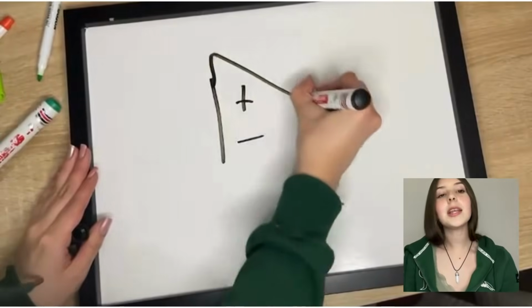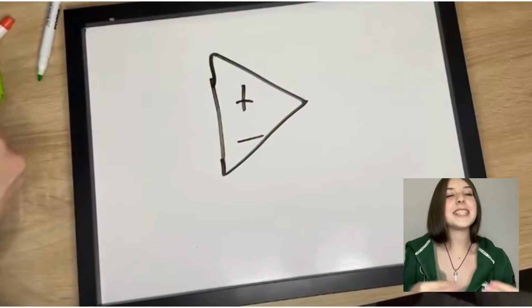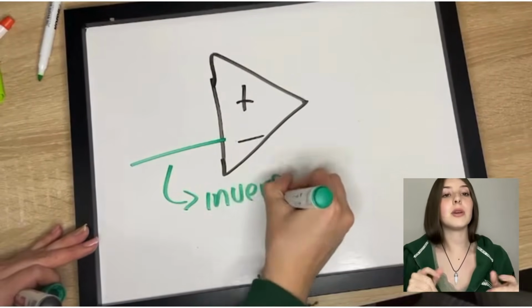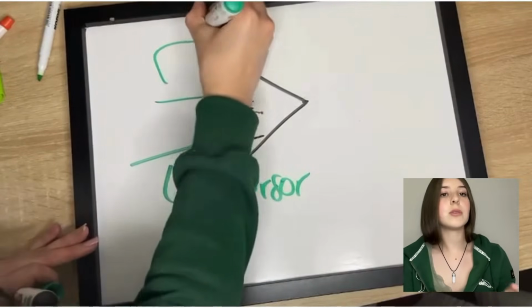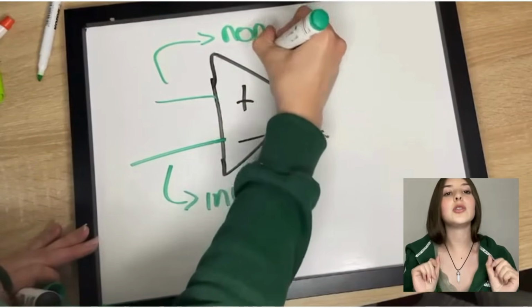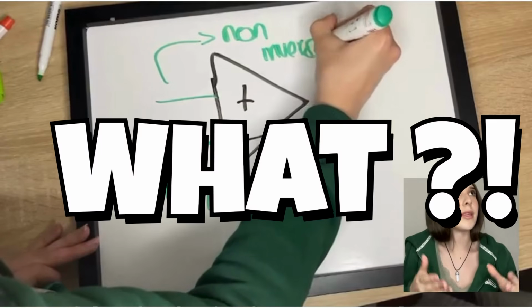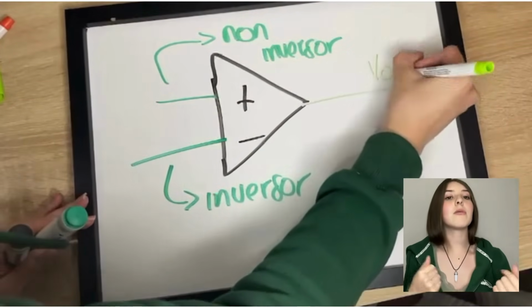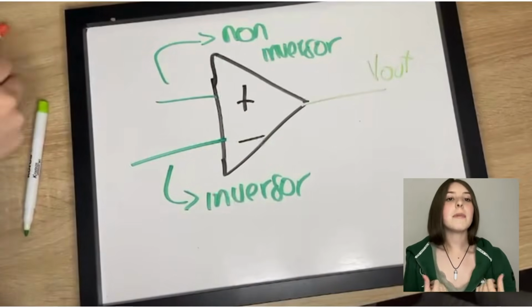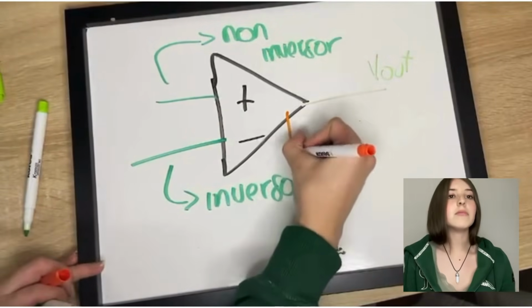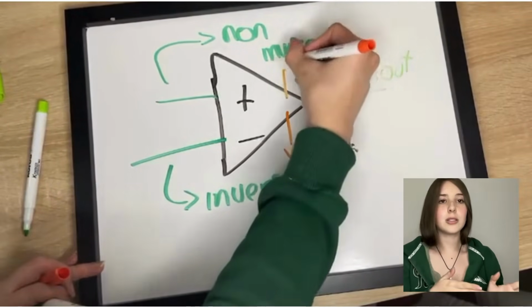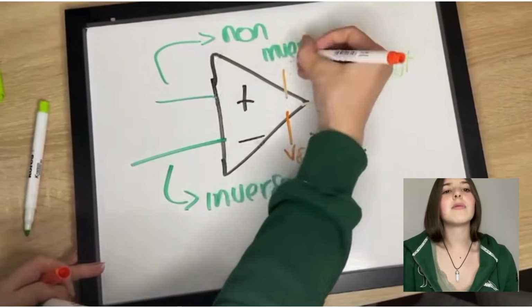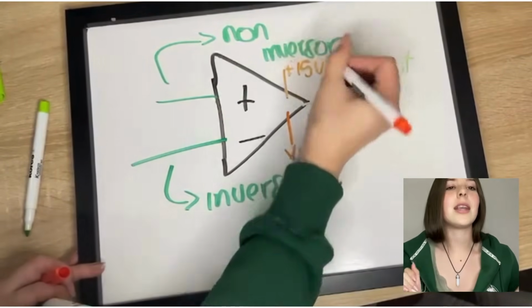An operational amplifier, or op-amp, is an electronic device that amplifies the voltage difference between its two inputs, the inverting input and the non-inverting input. But hey, this sounds kind of difficult, so let's start with the parts. I already mentioned the inputs. Now there's the output voltage and there's also the power supply, because without this it doesn't amplify anything.